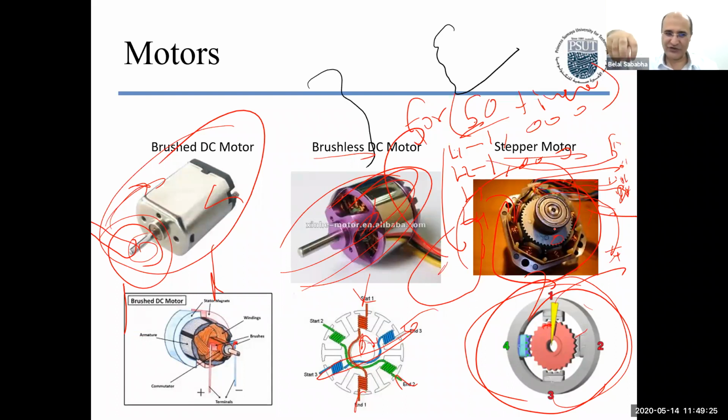Then the inkjet head starts moving back and forth for a distance that is well known. If you have an old one, just take it apart. The motors that move the feeder and the heads are usually stepper motors. If you don't want to wire them and do this math and loops, usually you can buy a stepper motor controller chip, where you just specify, for example, the angle you want to move, and it does everything for you, or the speed.